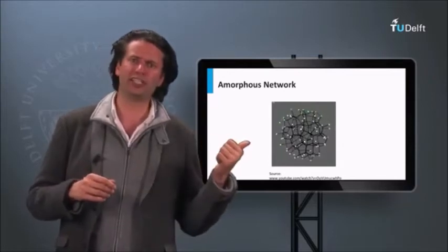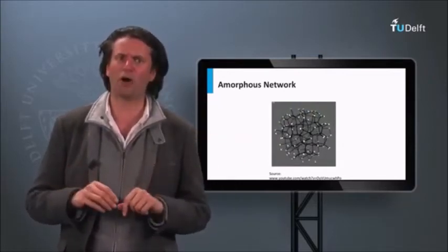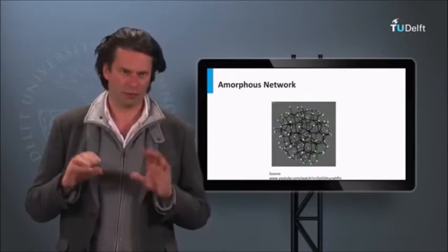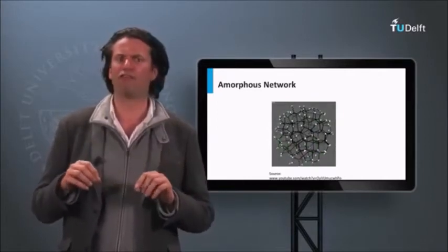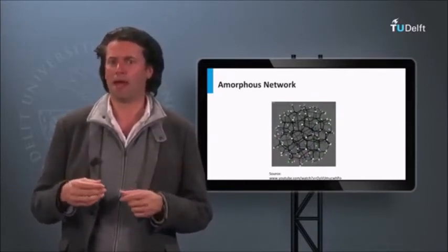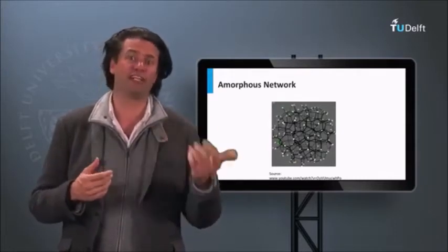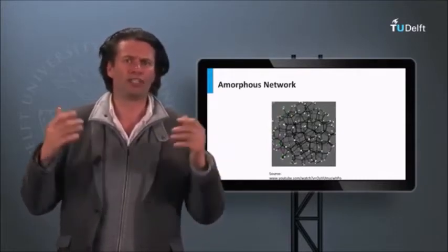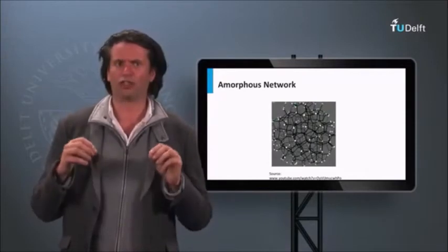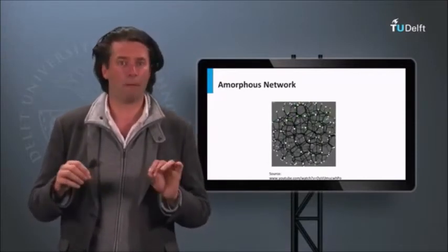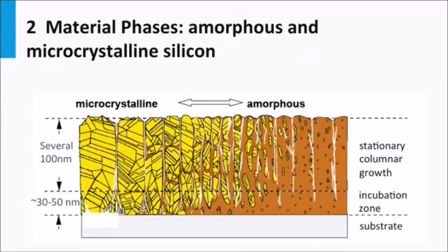Here you only see a disordered network which is only built up out of silicon atoms. In a real amorphous network you will have volume deficiencies in the lattice. Examples of volume deficiencies are vacancies, multi-vacancies or nanosized voids. The surfaces of these volume deficiencies are passivated with hydrogen.